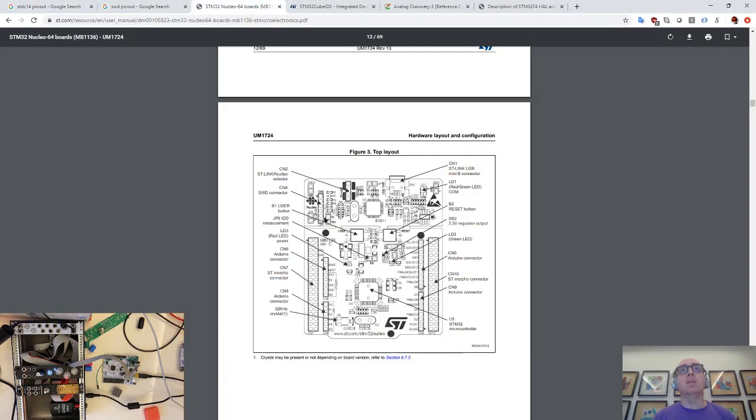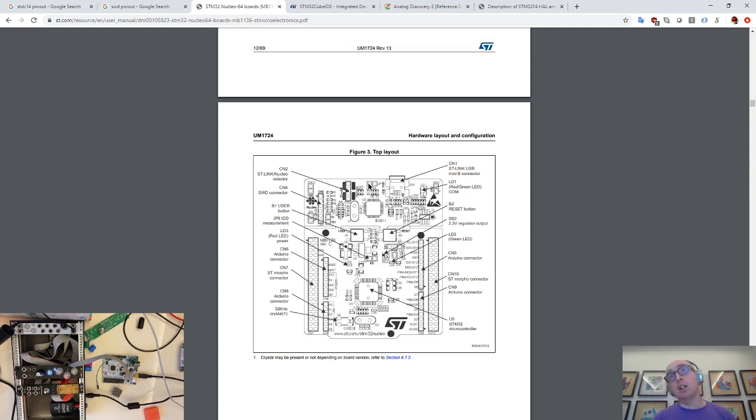As I say, the power goes in from your board, but conveniently this little header here seems to have 3.3 volts on it sitting there. So that's what my flying green wire attaches to. I jack that power out from this, which is powered by USB. So USB comes in, gets regulated. It's only meant to power this, but if you're running a small enough board, you can basically sneak a bit of power out of there and jam it into here and send it off to your board, which is what I do sometimes. Now I'm powering off Eurorack like a good boy because I have analog bits.